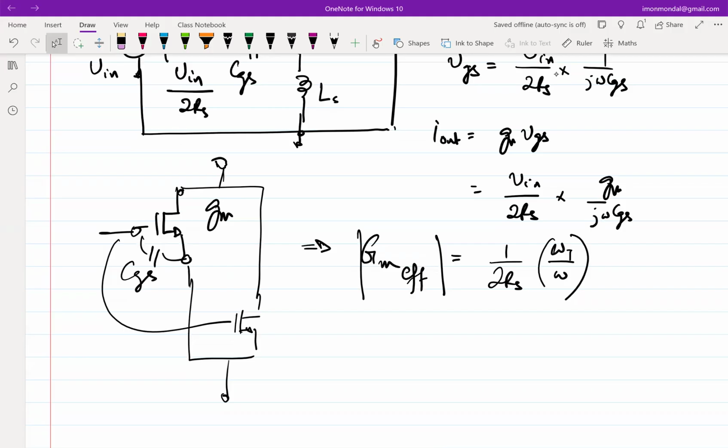What else can you do then? I cannot hear, I cannot see who is speaking. Okay, yeah. You can vary V overdrive. So you want to increase V overdrive or decrease? Decrease. So if you decrease V overdrive, does your CGS change to the first order?